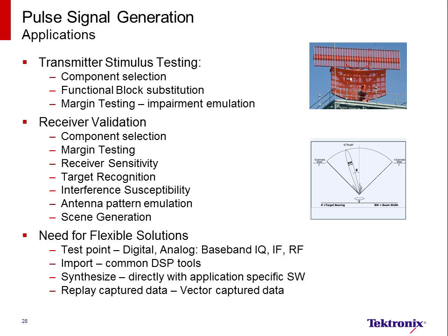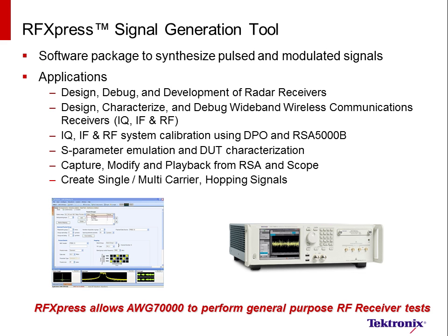Test tools need to be flexible to test at the available test access point, digital or analog, and at baseband I and Q, IF, RF, or microwave frequencies. In addition to synthesizing known signals, the flexibility to import waveforms from common DSP tools such as MATLAB and/or replay captured waveforms from acquisition tools like spectrum analyzers and oscilloscopes must also be considered.